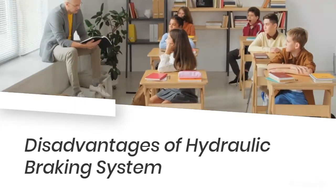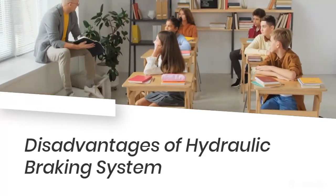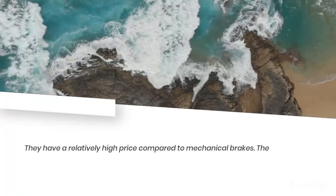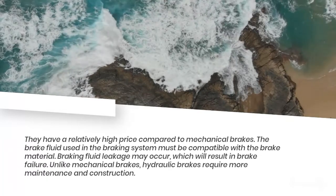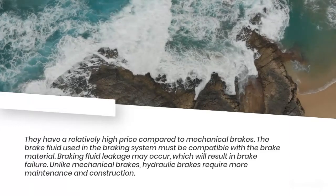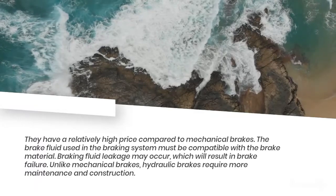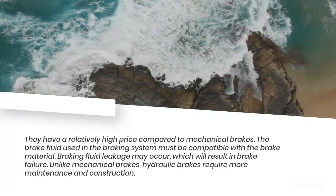Disadvantages of hydraulic braking system. They have a relatively high price compared to mechanical brakes. The brake fluid used in the braking system must be compatible with the brake material. Braking fluid leakage may occur, which will result in brake failure. Unlike mechanical brakes, hydraulic brakes require more maintenance and construction.